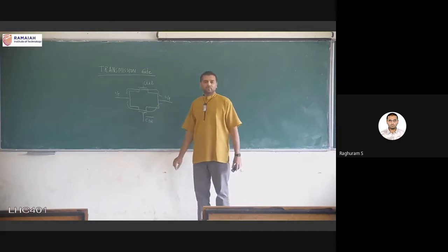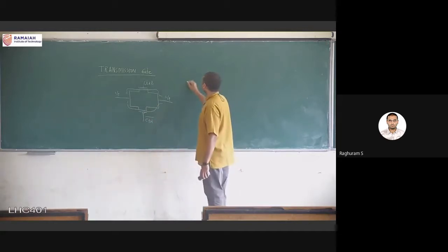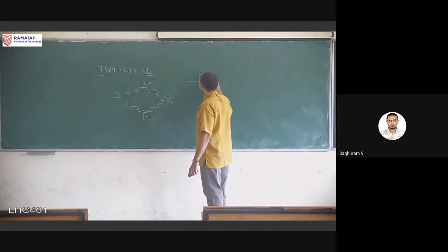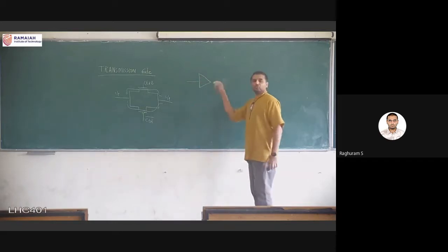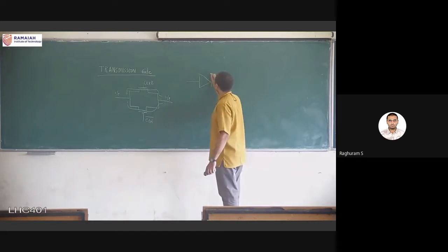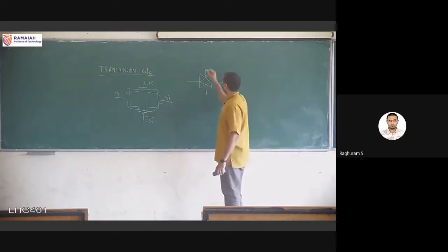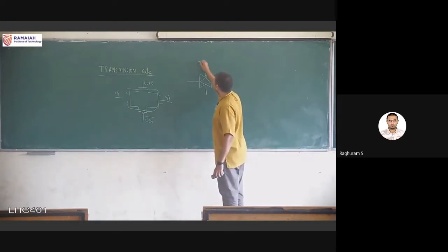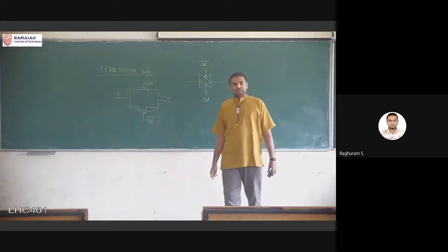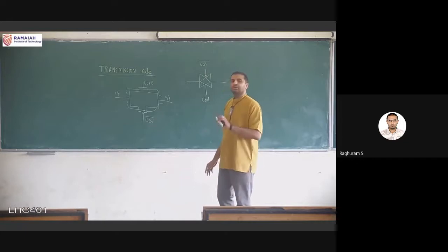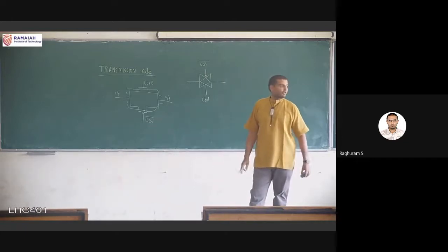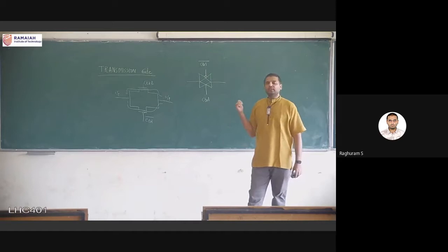And this is also represented by the circuit symbol, which is basically 2 triangles back to back, with the control signal and its complement. And this basically is nothing but input to output connection, same as pass transistor logic, but the only thing is only perfect values are propagated.